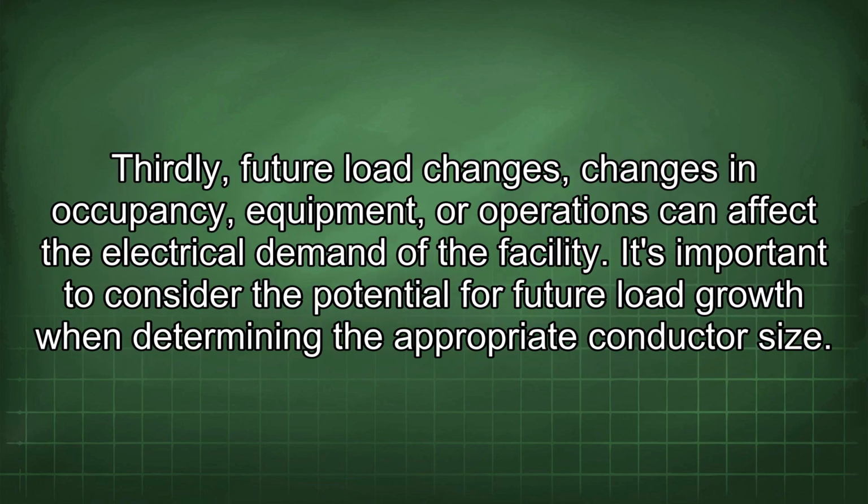Thirdly, future load changes. Changes in occupancy, equipment, or operations can affect the electrical demand of the facility. It's important to consider the potential for future load growth when determining the appropriate conductor size.